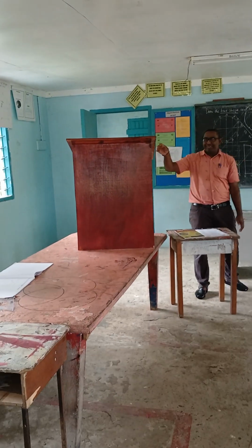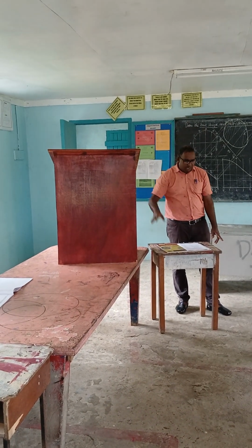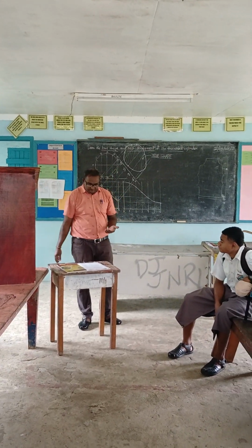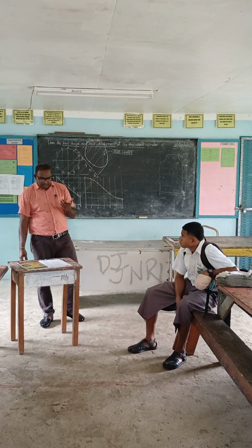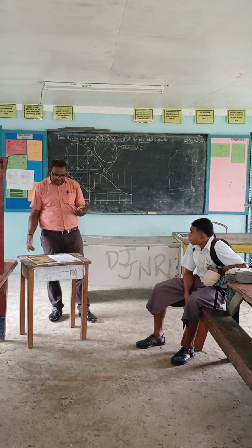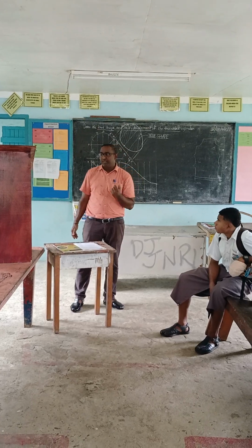So the project procedures that were followed were: one, measuring and marking, secondly cutting and ripping of the boards, thirdly smoothing the boards by the use of rasp and electrical belt sander, then assembling and fixing the pieces together, and finally applying stain, sanding sealer and varnish.